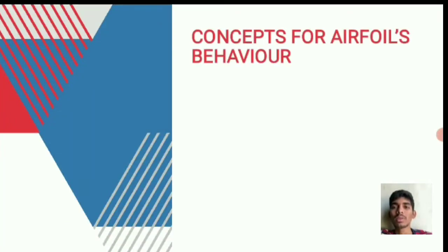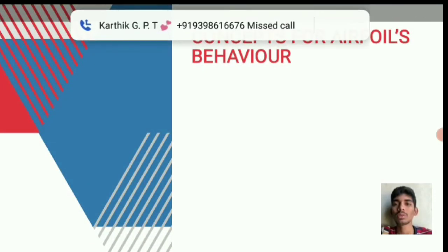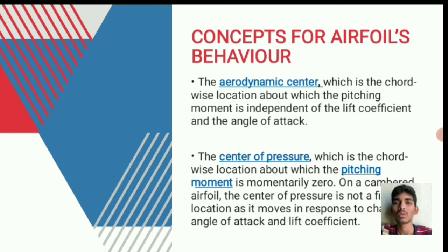Next, concepts for airfoil behavior. The aerodynamic center is the chordwise location at which the pitching moment is independent of the lift coefficient and the angle of attack. The center of pressure is the chordwise location at which the pitching moment is momentarily zero. On a cambered airfoil, the center of pressure is not a fixed location, as it moves in response to changes in angle of attack and lift coefficient.